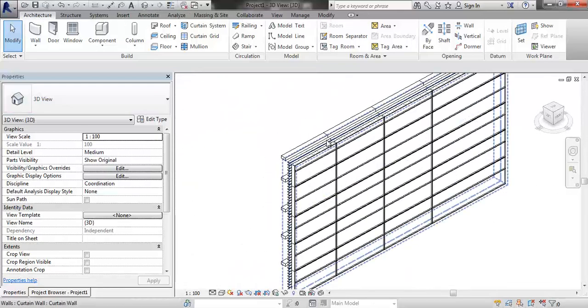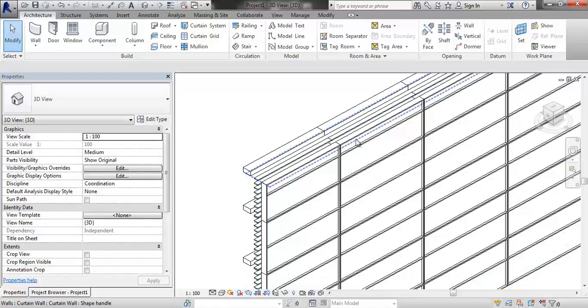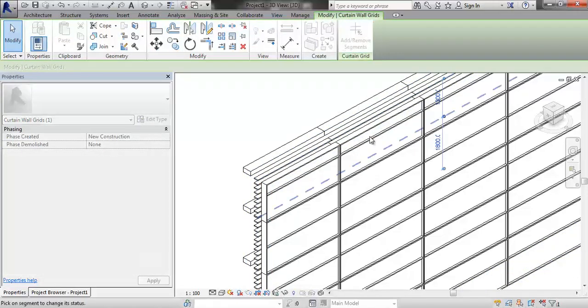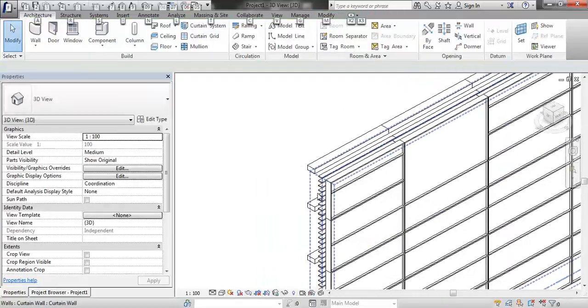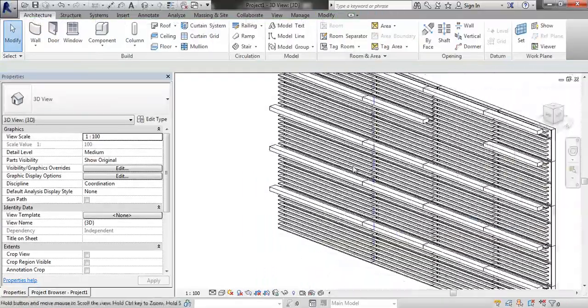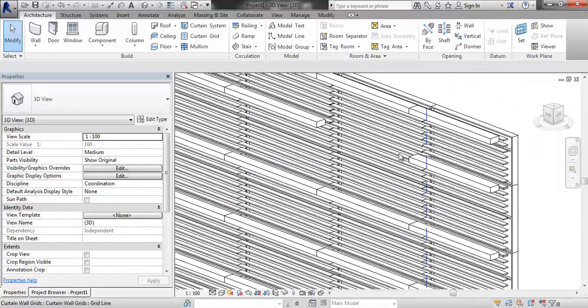So if I take my panel now, and let's say I'm going to delete out some grid lines. I take my lines and start removing segments. My grid cells for each one of these should stay, at least my louver array should stay somewhat visually apparent and right, but then it makes my panel bigger. Cool?